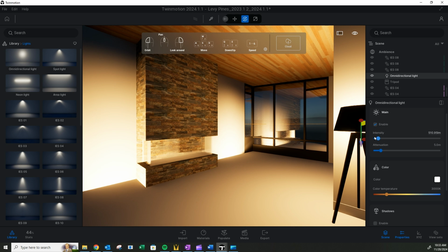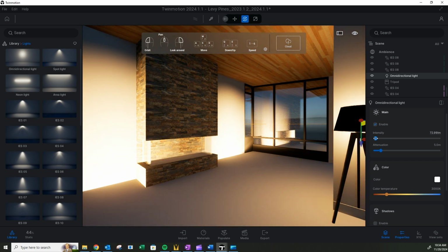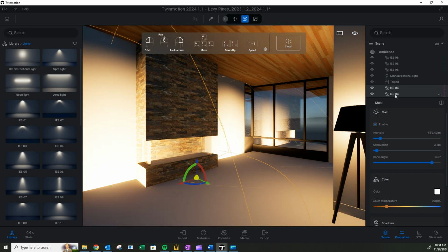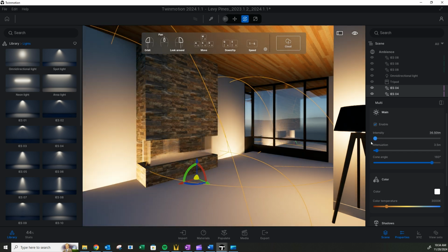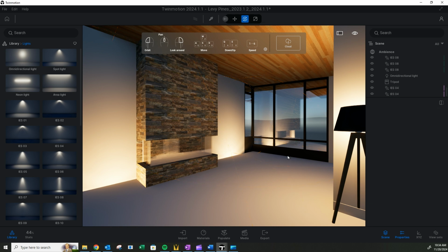So then you'd have to run your hot and neutral, and you'd also have to run a purple and gray wire, two low voltage wires to dim that 0 to 10 volt. Or sometimes, even now with the color changing fixtures, they're DMX. But ultimately, to help eliminate glare at nighttime too, you want to have them on a dimmer. That way you can dim it down and control the light through its maximum output, making it a little softer. So that's the three things: use optics, use shrouds, dimming control system.